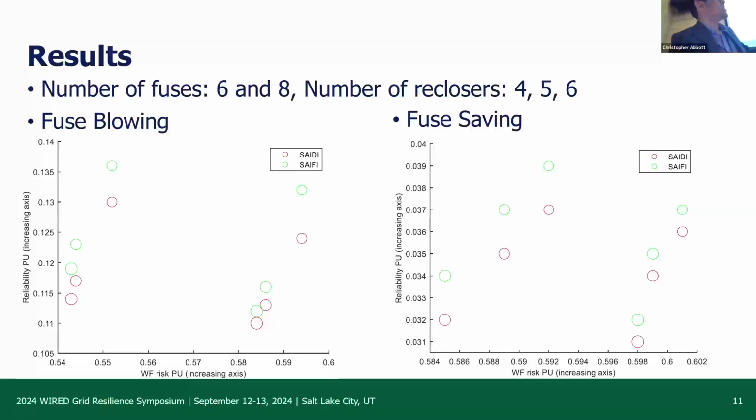So that is what utilities currently do when there is a risk of wildfire in their system: from the substation somehow remotely, or they need somebody in the field, they stop the reclosing option on the reclosers. But if we can have a way to find good locations for reclosers to minimize the wildfire risk, we don't need to do that, because if we disable the reclosing function, then we have poor reliability. I think that was it. Thank you very much for your time.